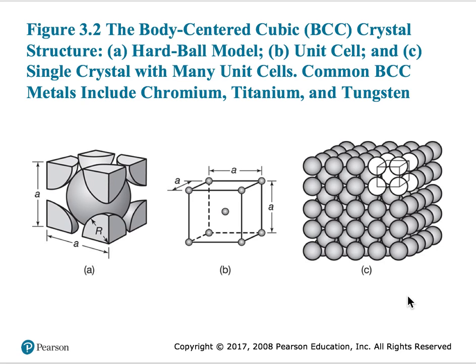And that hockey stick, the bottom of that hockey stick will tell you the maximum stress that this component should be experiencing in service. And that is because these materials will tend to creep much faster than a face-centered cubic type of material.